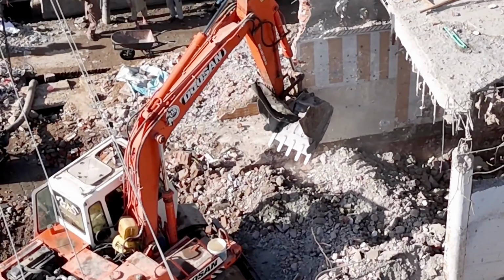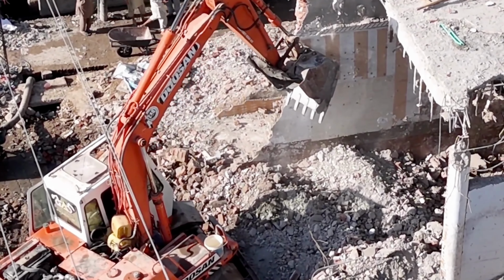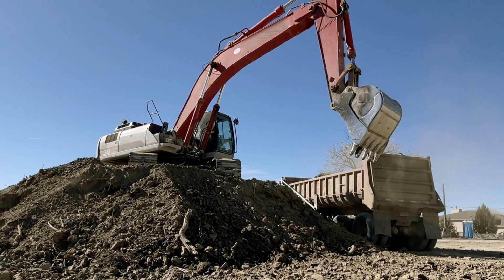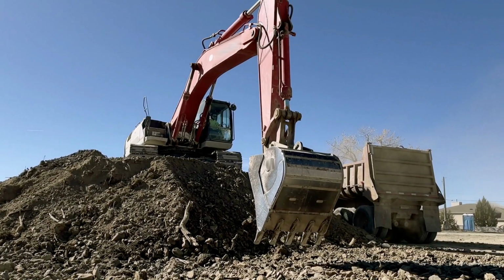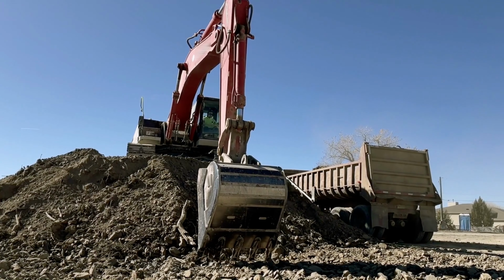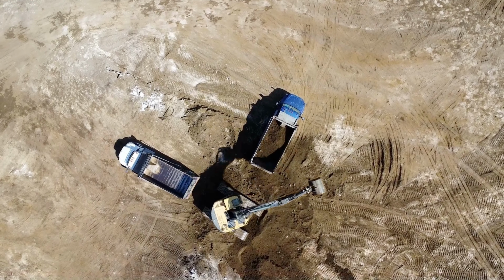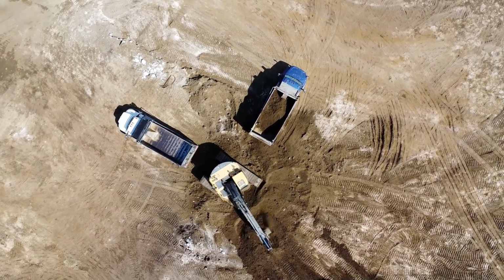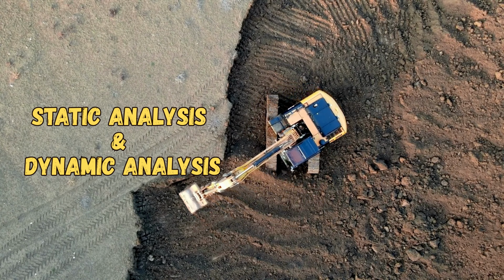However, excavator stability is not governed only by static conditions. In real working environments, the machine is constantly subjected to dynamic effects. For example, when the excavator swings a loaded bucket from the digging point to the dumping location, the rotating mass generates centrifugal forces and inertial loads. These dynamic forces can temporarily shift the effective center of gravity and increase the tipping moment acting on the machine. Similarly, rapid acceleration or deceleration of the boom, arm, or swing system can introduce additional dynamic loads that influence stability. Because of these factors, engineers must analyze excavator stability using both static and dynamic stability criteria.